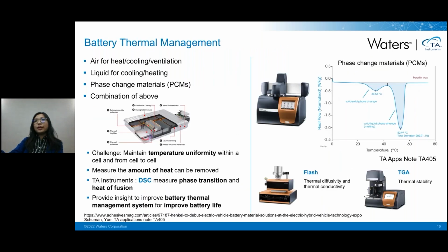After you understand a lot of the heat flow signals, such as the heat capacity, you want to also scale this up into different cells. People also need to understand the heat parameters to design the battery thermal management system. There are a couple of battery management systems that have been in the market. For example, using air to cool the battery cell.